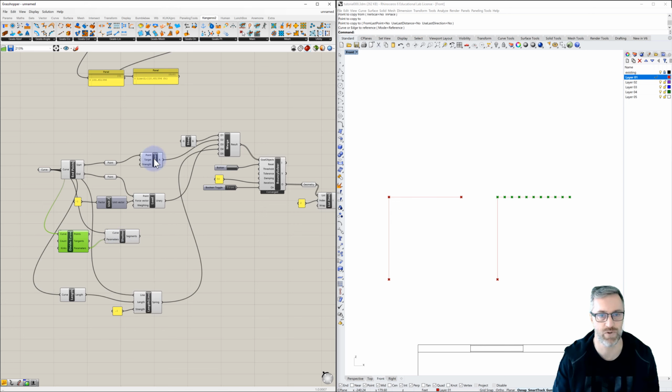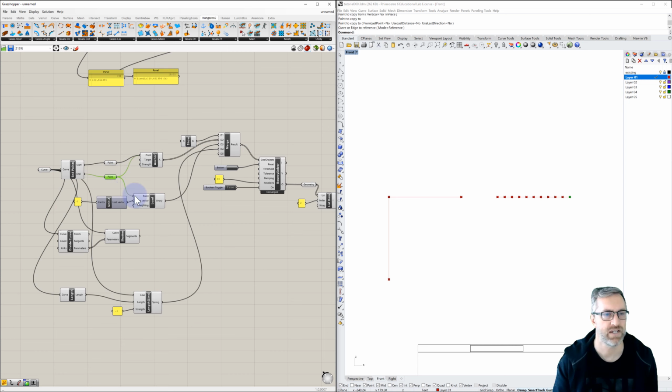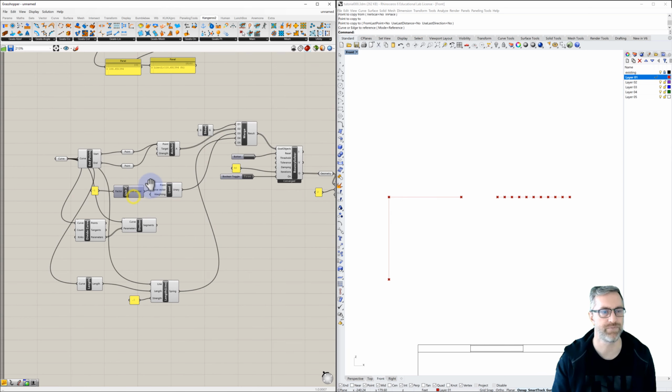Now we have our anchor points. Let's add our end point. See, we have our start point and our end point. Let's add our end point holding down Shift to the anchor, because we want the two endpoints held and we want to let this cable drape. And from the load, let's disconnect that point from those loads.